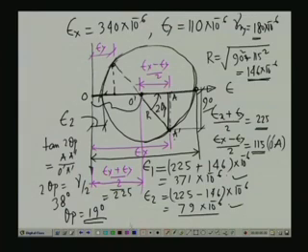So, if it is oriented at an angle of 30 degree, in the Mohr plane it is twice the theta. So, it is 60 degree. Now, with reference to the positive epsilon x and gamma xy by 2, if we orient by 60 degree, this is the 60 degree point, and if we join the line from center to this, we get this particular point, which is the direction where we need the strains. This is the normal strain and this is the value of the shearing strain by 2, gamma x dash y dash by 2. Now, this particular angle is 38 degree, and this total angle is 60 degree. So, 60 minus 38, if we call this alpha, alpha is equal to 22 degree.